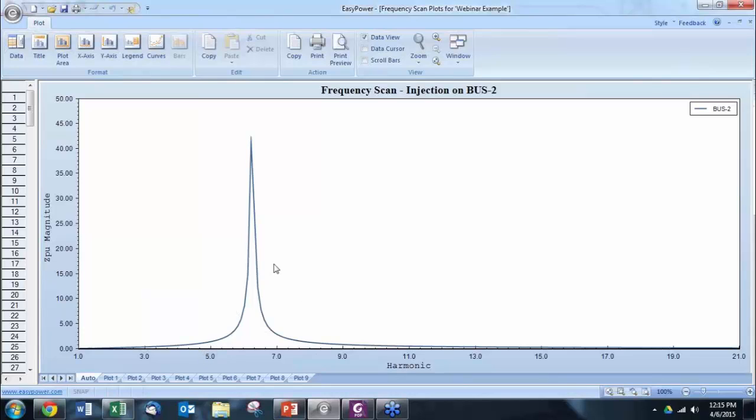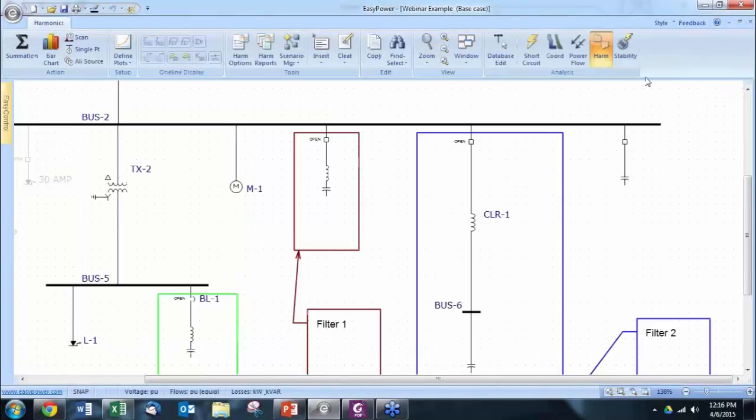And that is a common misconception because sometimes people say that capacitors produce harmonics, and that's not true. Capacitors do not produce harmonics. They only amplify harmonics. And you can see that in here. This is a very, very valuable tool for checking out how your system will react to harmonic resonance. I see here that the most important harmonics, which are the 5th and the 7th, and everything in between, will be amplified. 11 and 13, not so much. So that's not a solution.